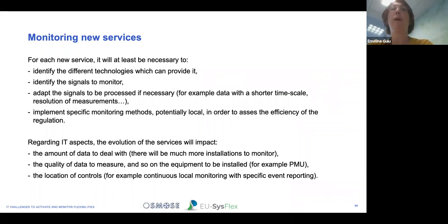So grid forming function is part of the set of levers used to maintain the equilibrium of the system. Indeed, new phenomena are going to appear with the increase in renewable energies connected via power electronics. One of these phenomena is the decrease in inertia and consequently the increase of frequency deviations for the same event.